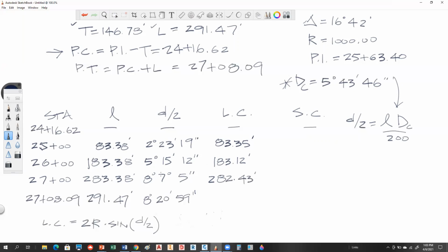Okay, so again, notice how it's starting to change quite drastically. Then the last one has the biggest amount of deviation, 290.43. Okay. What you guys will definitely notice with this, the smaller the radius is, the more these are going to disagree, okay? The larger the radius is, the more these are going to agree, because it has to do with the size of the arc. Is everybody okay with that?